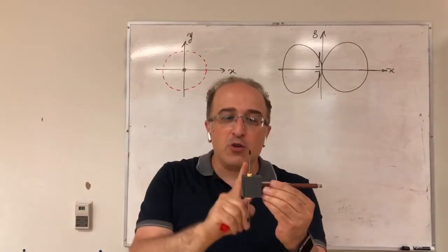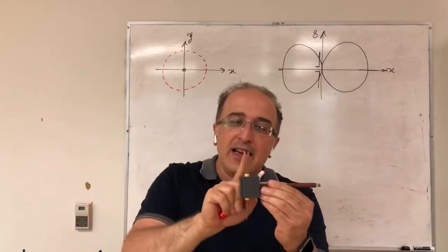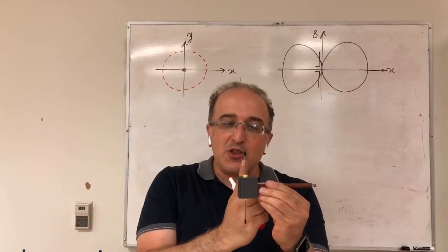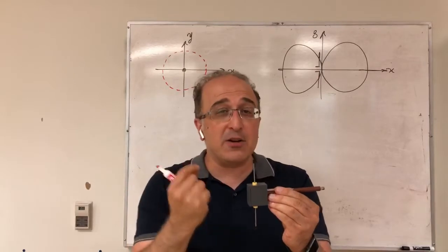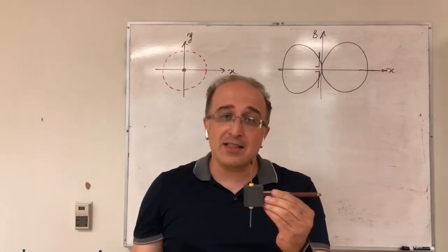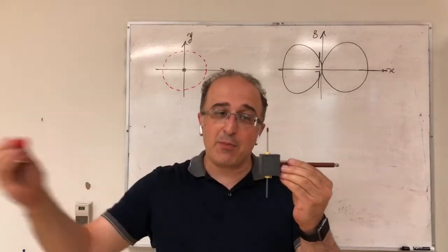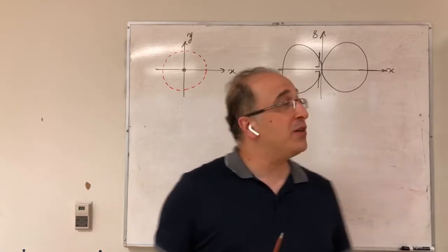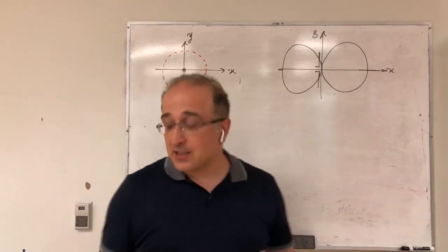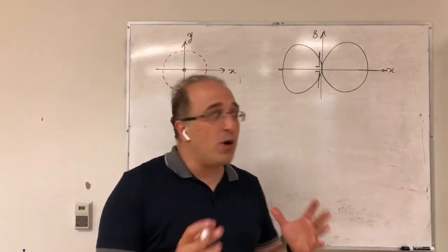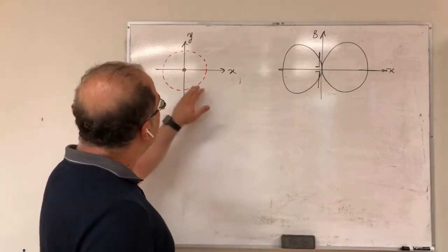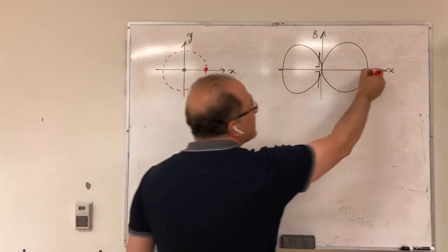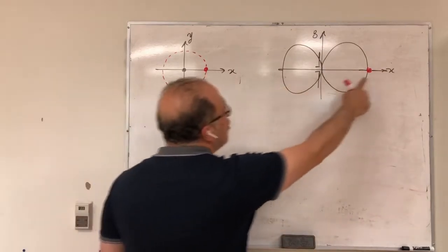So if you want to use this antenna to communicate in this direction, that's a mistake, because this antenna has extremely small radiation and theoretically zero radiation along its axis. And most radiation happens in this direction. So this is something that you should keep in mind, that this radiation pattern is gonna tell you. And something I want you to notice here is that this point here, which is on the x-axis, is exactly the same as this point. So remember, these 2 points are exactly the same.